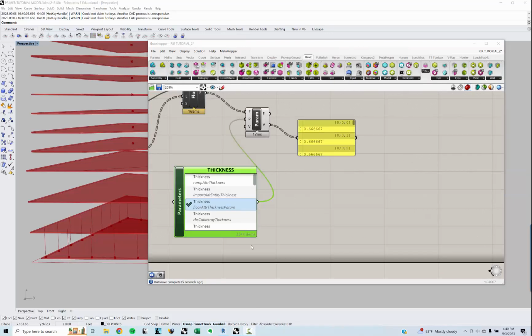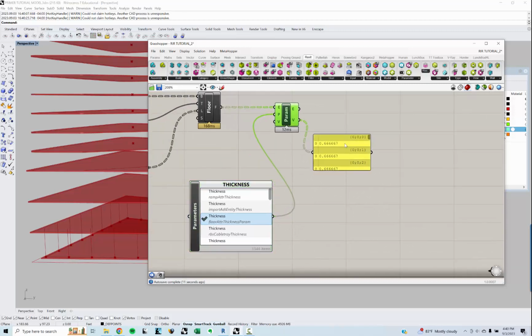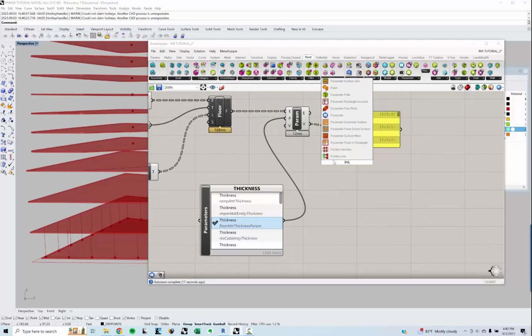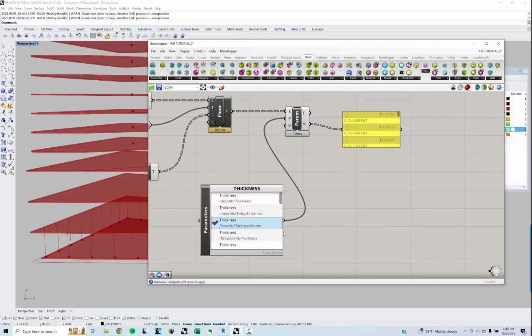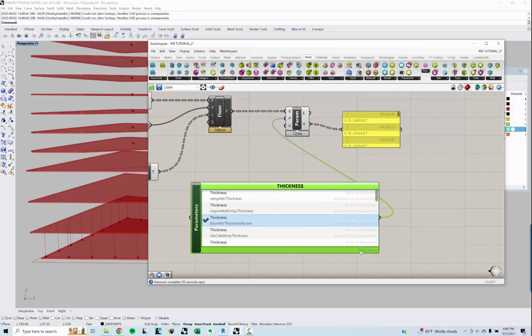All right, I'm back, and I figured this out. I knew there was a way to do it. So sometimes it can be difficult to find specific parameters using that parameter dropdown, which was this one that I was using before. So within parameter, there's this built-in parameters, which is just a massive list of all different kinds of parameters that are within the whole entire file, so there's over 3,000. You can click up here and search, and I eventually found floor attribute thickness parameter. And so if I plug that into here, I get the thickness of them.